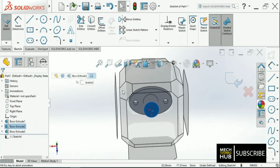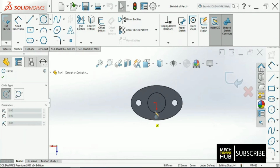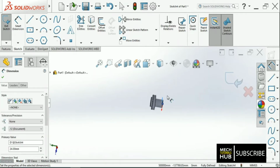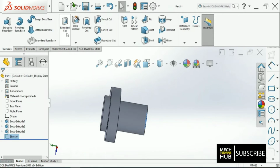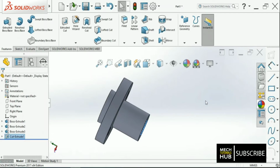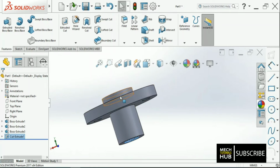I'll keep it in this mode and remove some material here of dimension 24. As it is a material removal, exit the sketch and go to extrude cut, and material needs to be removed. I just remove it through. Okay, this is fine.